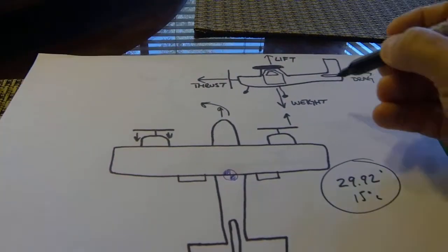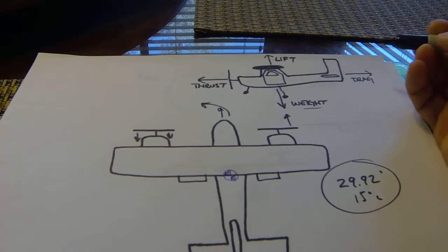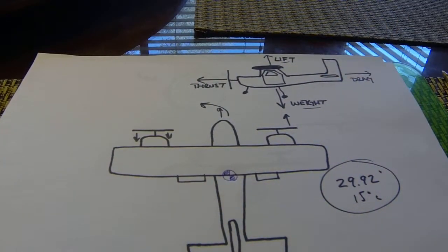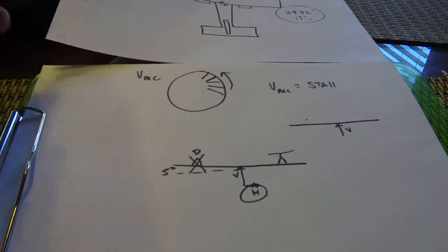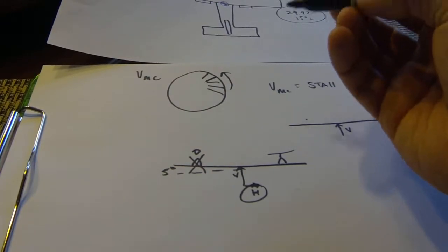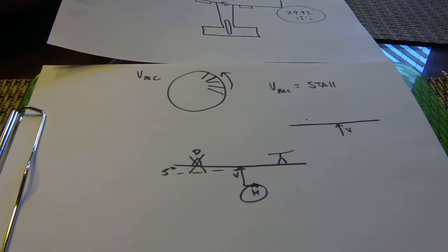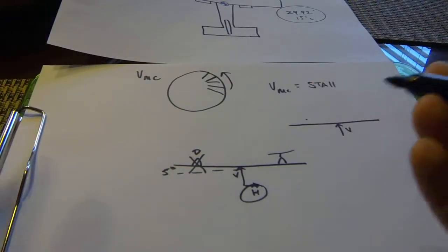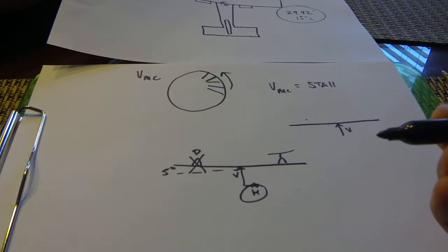It just makes sense. If we're extremely light with our weight, then our lift is going to be light also, and we don't have that spare lift, I guess you would say, to provide a large horizontal component of lift on the vertical stabilizer, on the rudder, to give it more authority.